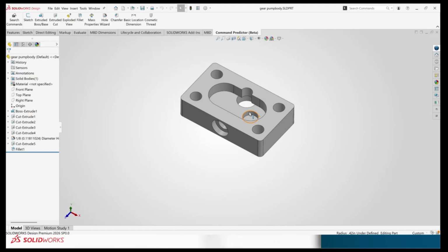So let us see how this option will work in real time. Okay, now we can see a machine part here. If you want to generate the technical drawings manually, it will take a lot of time to relocate the slots and grooves. For that purpose, SolidWorks came up with a new option called auto generate drawings. In just one go, you can create your technical drawings, but you just need to put in minimal effort to rearrange and give the detailed annotation. Let's see how it will happen.